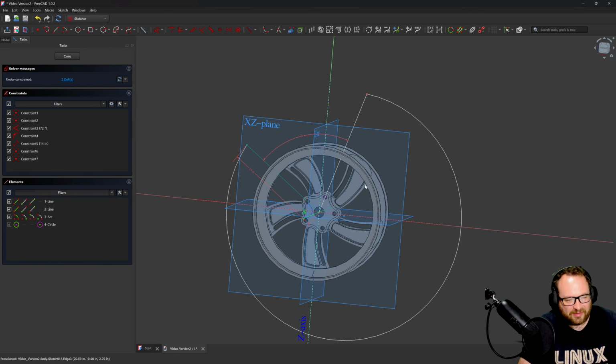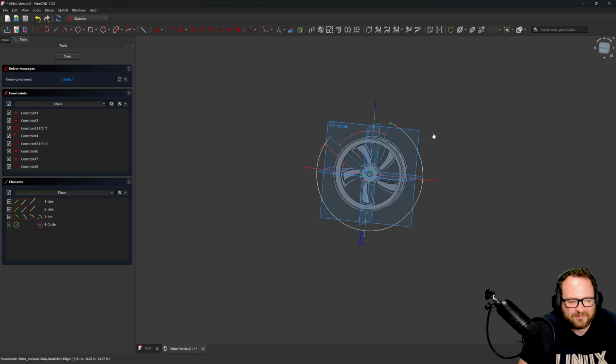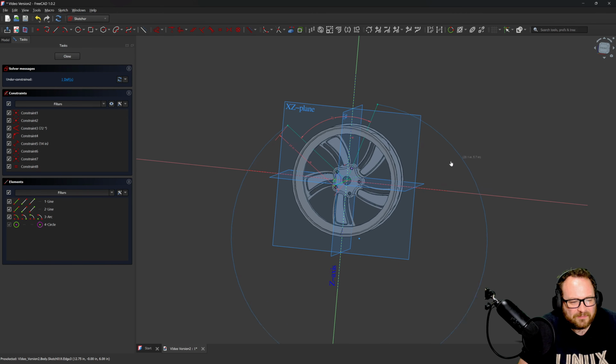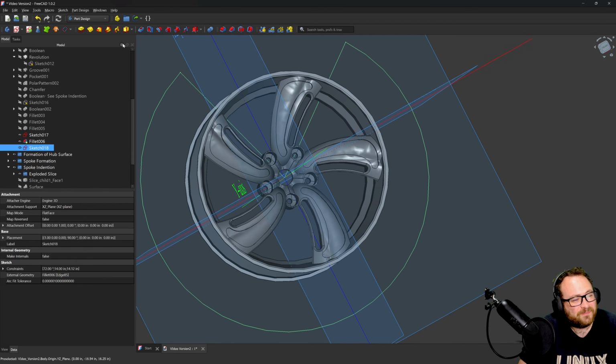That's going to cut out exactly what I want and nothing more. So did that equal not apply to that line, I guess? Okay. Yeah, we're fine. I'll just give that a dimension so it's fully constrained, but we're obviously cutting out what I want. So if I cut out that section of the wheel and I say pad.